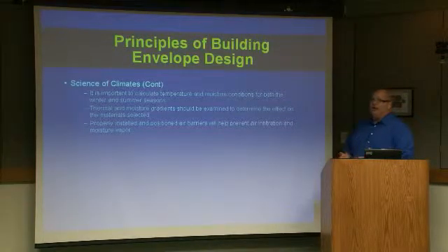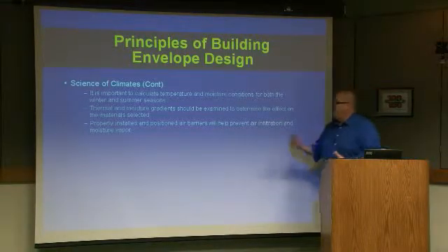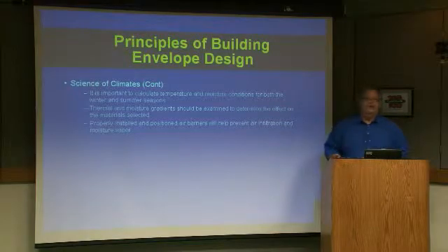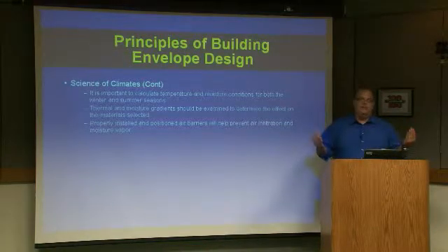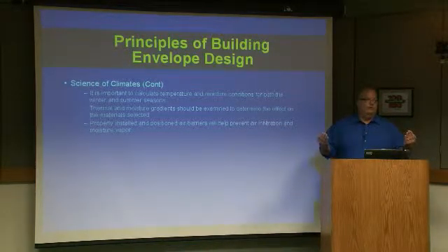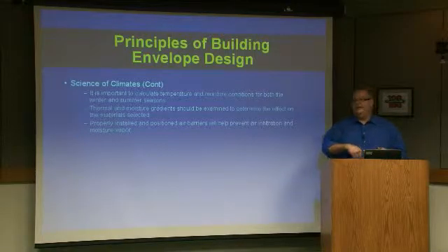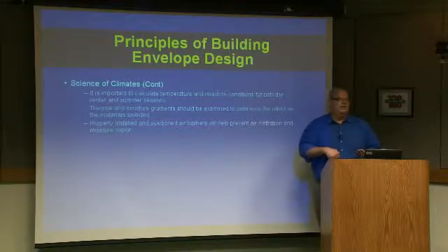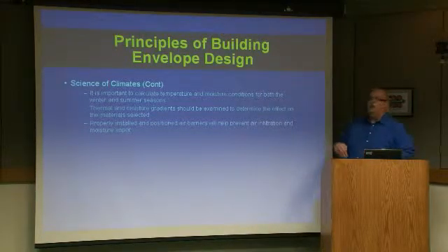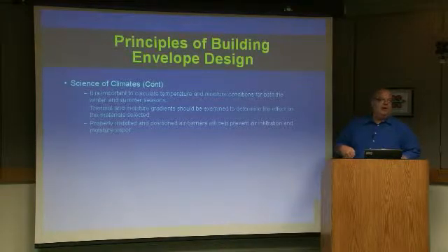If we're going to have a rule of thumb that we're going to use, there's two in this case we've got to depend on. The first one is one of the oldest ones we have in construction. Never create double vapor barriers. Never have two, because if water gets in between, it's not getting out. So we don't do that. So we know already we don't want to be below 1 US perm on that outside layer, which means peel and stick membranes are very dangerous.